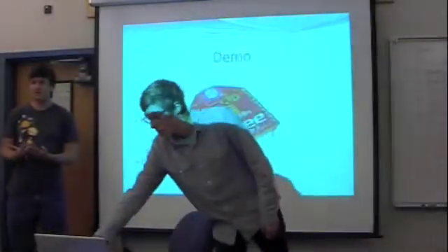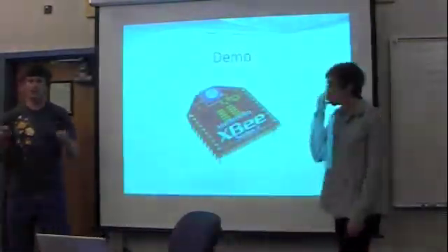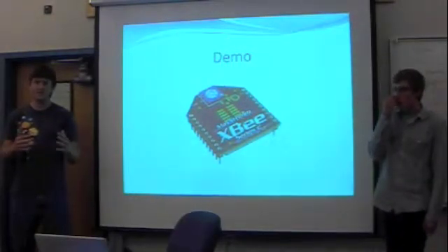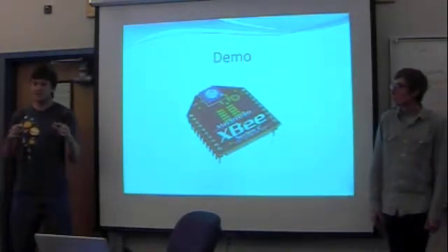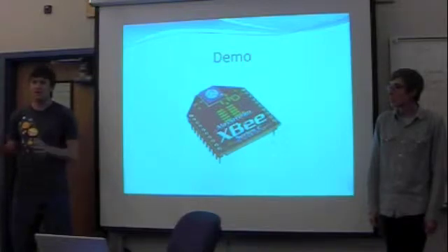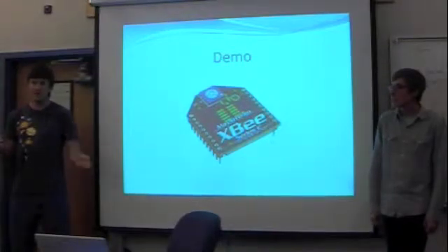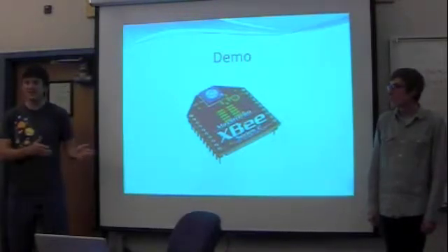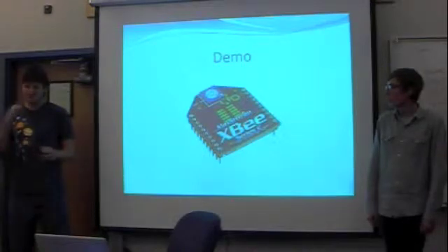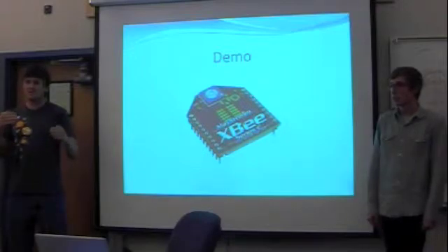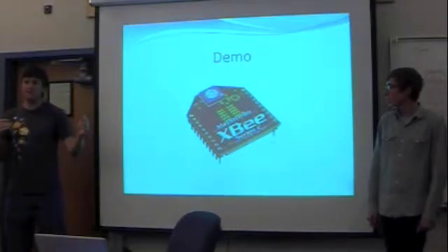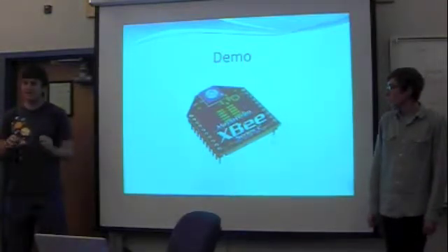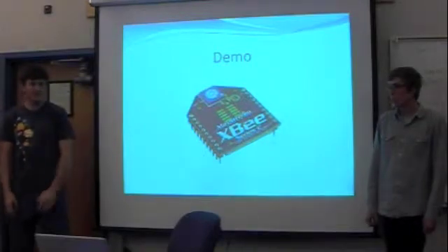And so testing the board, we used the LEDs when we first started out to test. So we would display the scan codes from the keyboard or the character that we're trying to send to make sure that it's working. And once we had it working pretty well, we could test it by sending messages and seeing if they got the message. Once it was working perfectly, we took it outside and found out the maximum range outside, and then we were playing indoors to find out the range. So that's how we did it. Yeah, it was pretty handy.